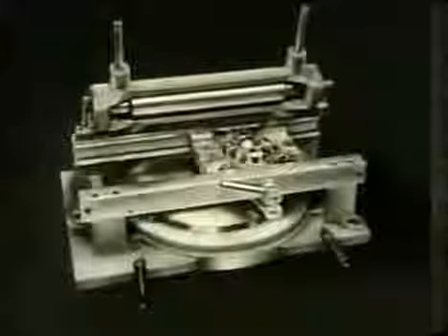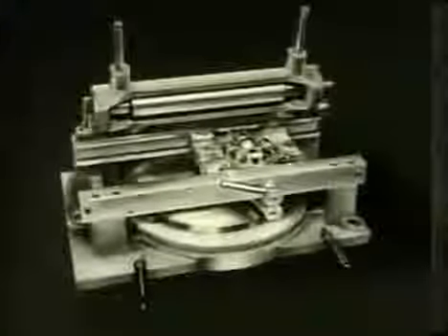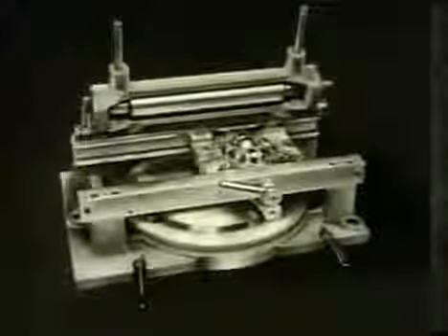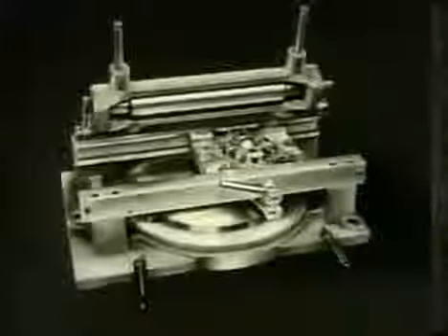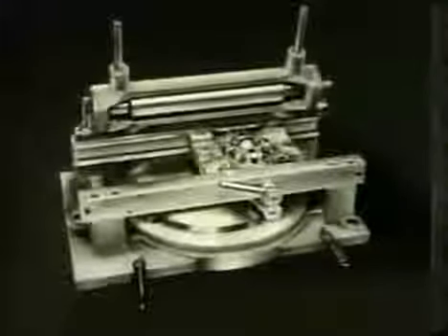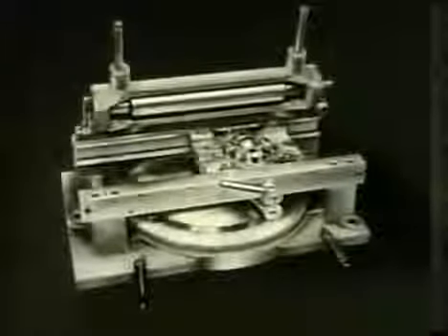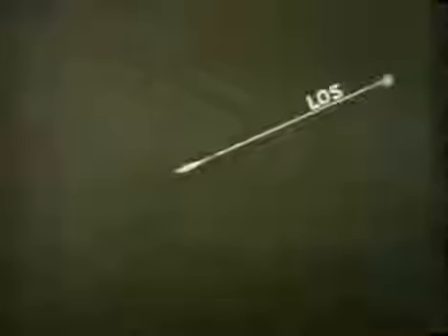This is a disk-type integrator, one of several different types. They can do many jobs. One of the simplest, the job in range keeping, will give you a pretty good idea of what an integrator can do. An elementary example of range keeping is one with stationary target and with ownship moving at constant speed along the line of sight. The problem starts with an observed initial range.